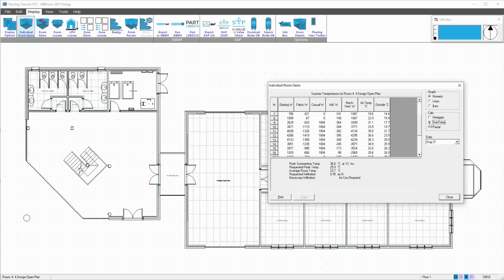The summertime temperature can also be viewed. We're now getting a cooling effect. It was 43 degrees, now 36 degrees. If we apply that extra 3 kilowatts of cooling, that will also bring the room down to the specified 22, 23 degree set point which we've applied.